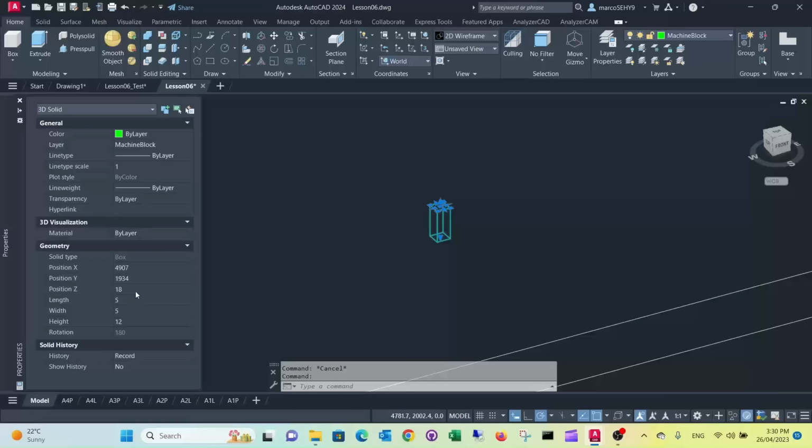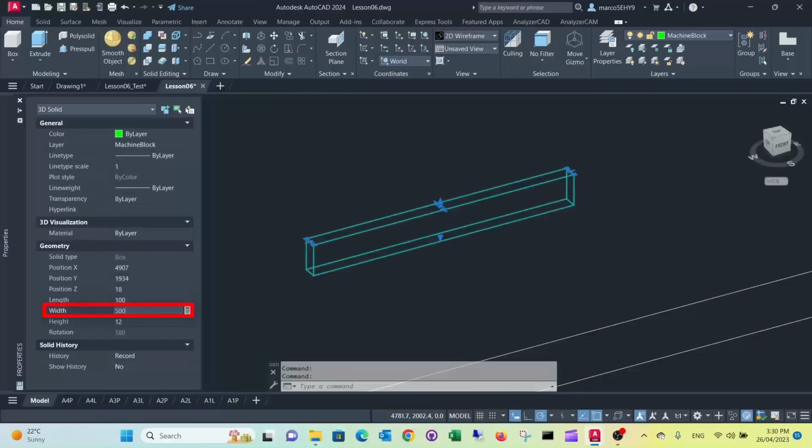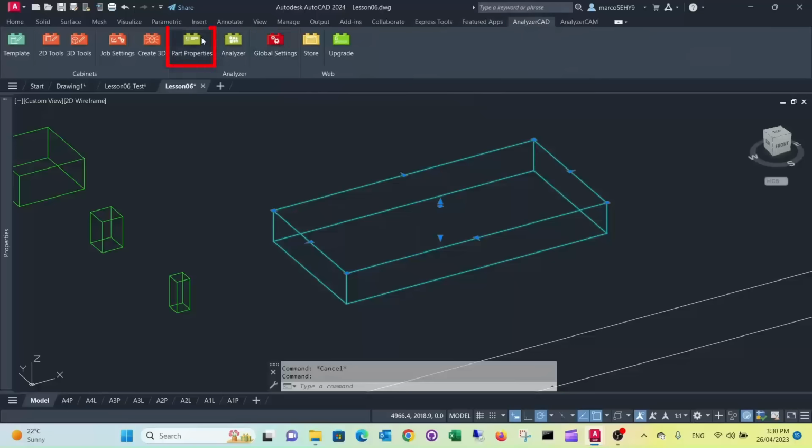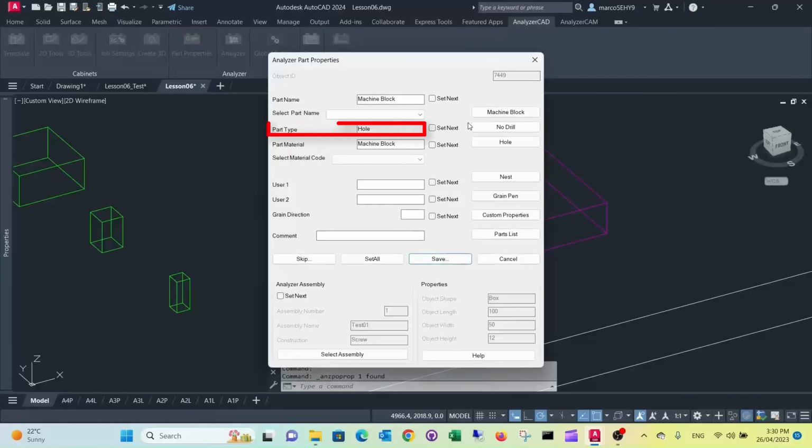Click at it. We want that pocket 100mm long and 50mm wide. Now it's obviously not a circular pocket anymore, or a hole, so we can change this to just an ordinary pocket.